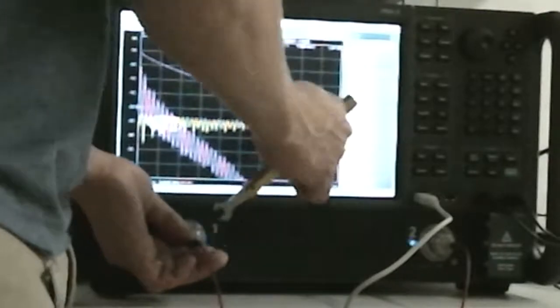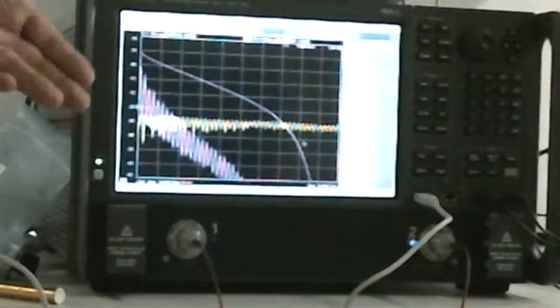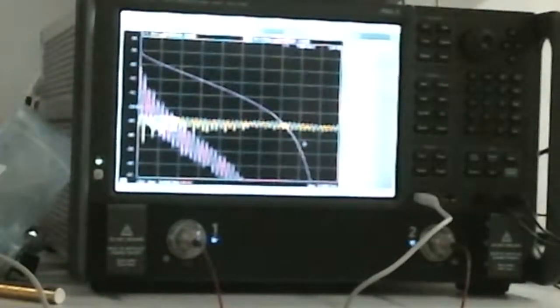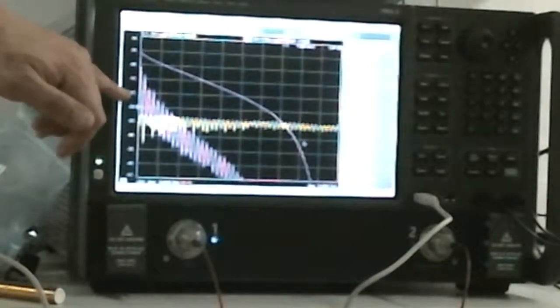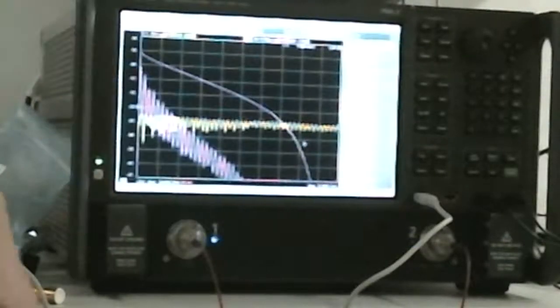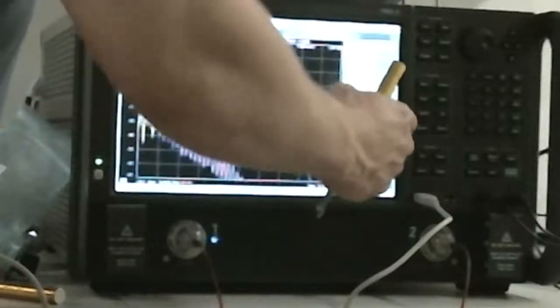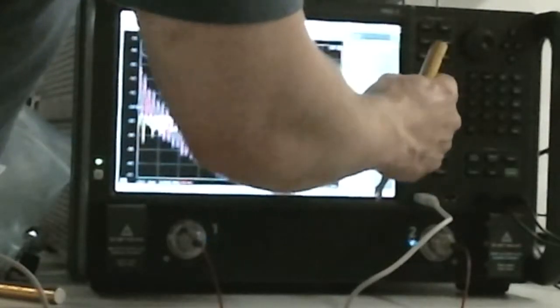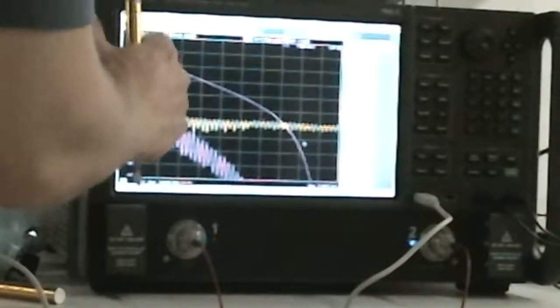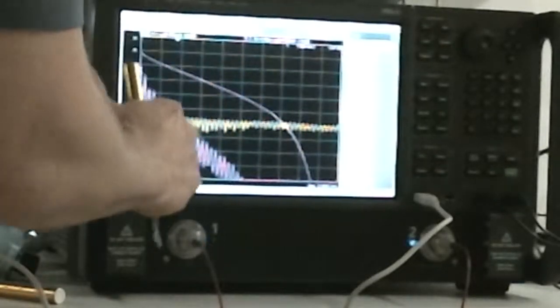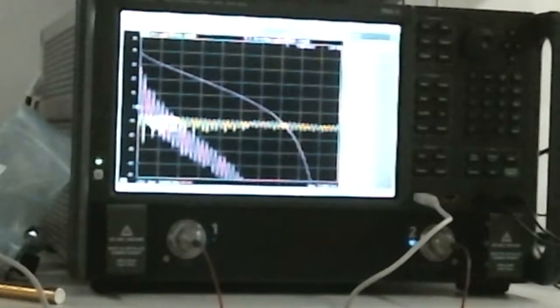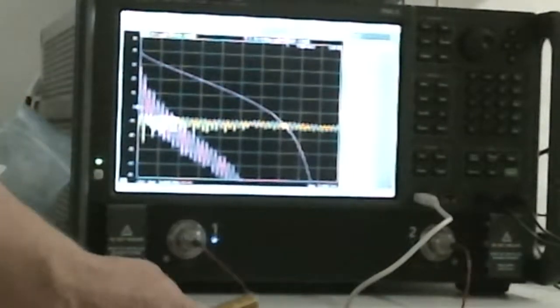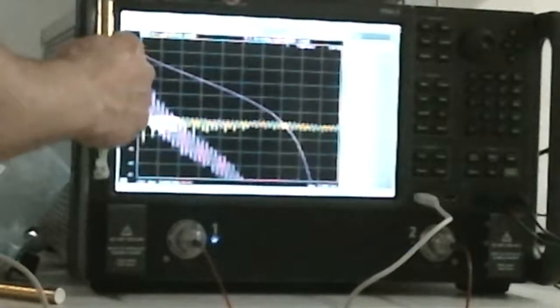Again, I'm zooming in a lot here, so if you just want to get the rough response of this cable, you can say, yeah, this cable has about 2.5 dB of insertion loss. Again, if I go back and look at it, this is actually the S11, right? So this is actually a minus 10 dB of return loss. So it's not the worst, right? That's the return loss of the cable, but the insertion loss of this cable, right?